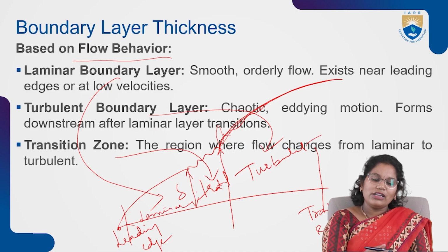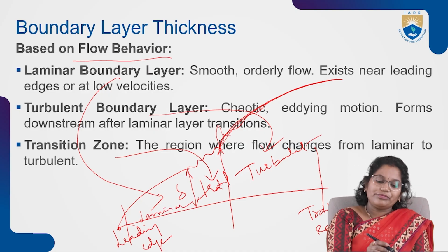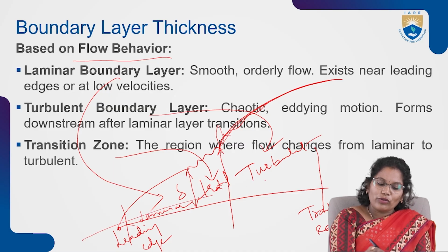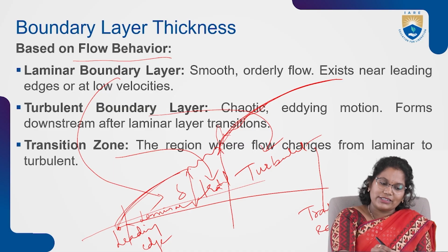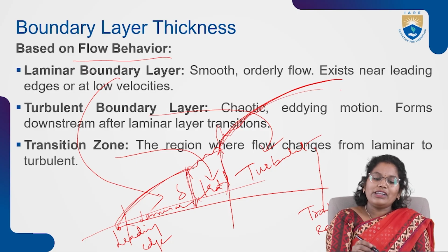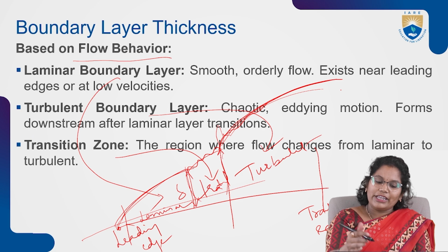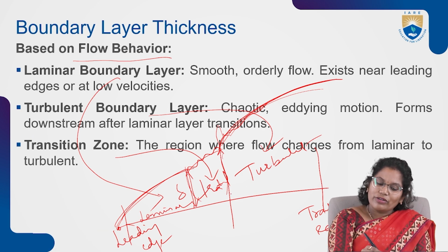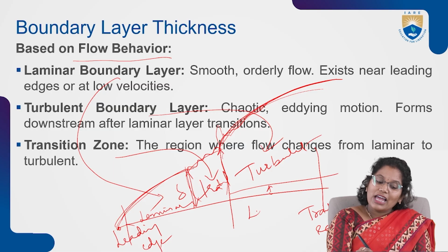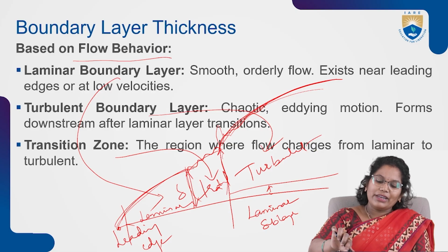Yes, these all depend upon how the flow varies. Here also we see types of boundary layer thickness. This is the laminar boundary layer. Till here, this is the transitional zone. After that, the turbulent boundary layer. Right? Again, in that turbulent boundary layer, as we discussed in the previous session, we see a laminar sublayer.